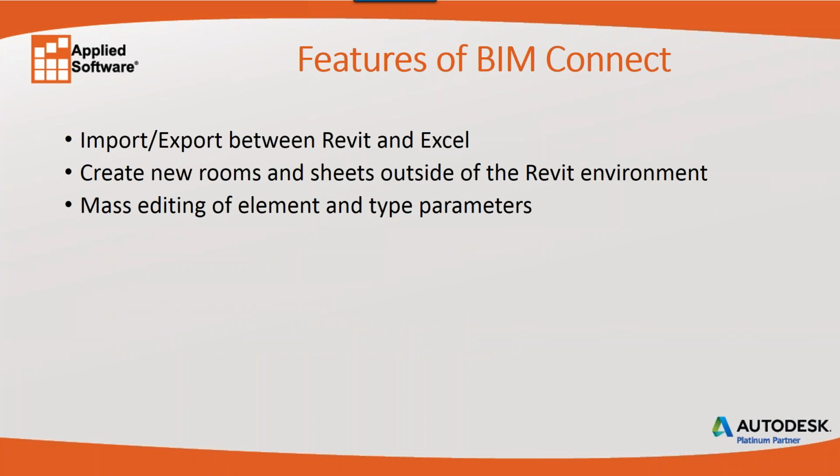So the current version of BIM Connect, what's available now, has the ability, of course, to import and export between Revit and Excel. We can also, in BIM Connect, create new rooms and sheets. So you don't have to be in the Revit environment to add a room or add a sheet. You can actually do it inside of BIM Connect. And it gives you much more ability to do mass editing of elements and types, changing their parameters.